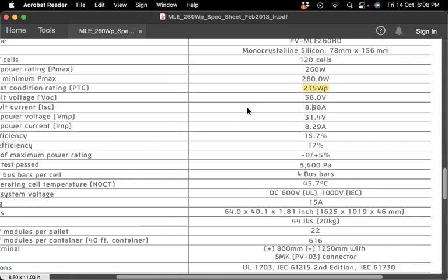And typically, if this current drops to 4 point something ampere, then that means that your irradiance is half sun or 500 watt per meter square, and so on. So this number, the short circuit current, which is easily measured in any solar cell using just a multimeter, can be a very good indication of the level of irradiance of the solar cell or this place.